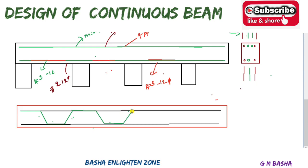If you observe clearly, what is the purpose of providing the crank in a single bar? The reinforcement required is 3 bars for the bottom side and 4 bars for the top side. If you bend 1 bar like this, it covers both the top side and the bottom side with that one bar. So this is also one procedure.